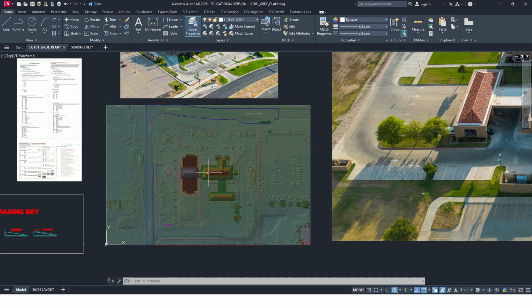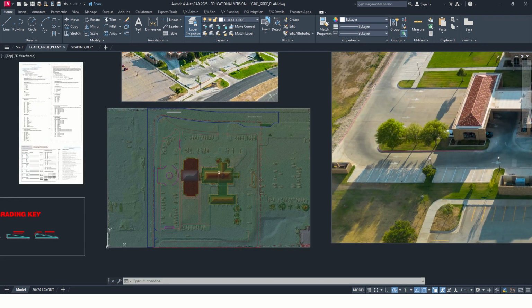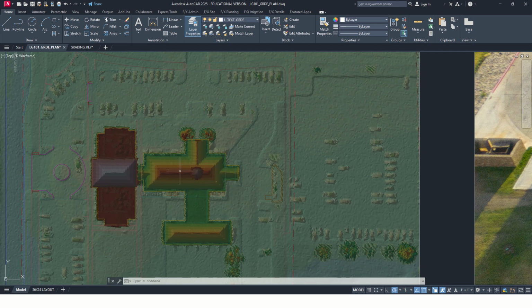What a lot of times civil engineers will do, instead of using the grade that's above sea level, because you're talking thousands of feet here in Lubbock anyway, not if you're in New Orleans. What they'll do is they know there's only about 3 feet, maybe 4 feet worth of fall in this entire site. So they're just going to say your FFE, which stands for what, Braden? Anybody? We're looking at the building. FFE is exactly finished floor elevation. Nice, Josh.